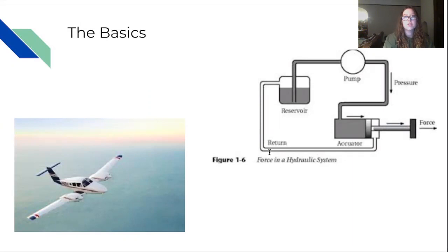The reservoir is where hydraulic fluid is stored, and if there's ever any question about the quality of hydraulic fluid being used, it should be drained, flushed, and refilled. The reservoir for the hydraulic fluid must be able to hold a slightly greater volume than just the hydraulic fluid to account for expansion as temperature increases. The reservoir will also have the ability to release air from the fluid to make sure that there is no air entering the hydraulic systems.